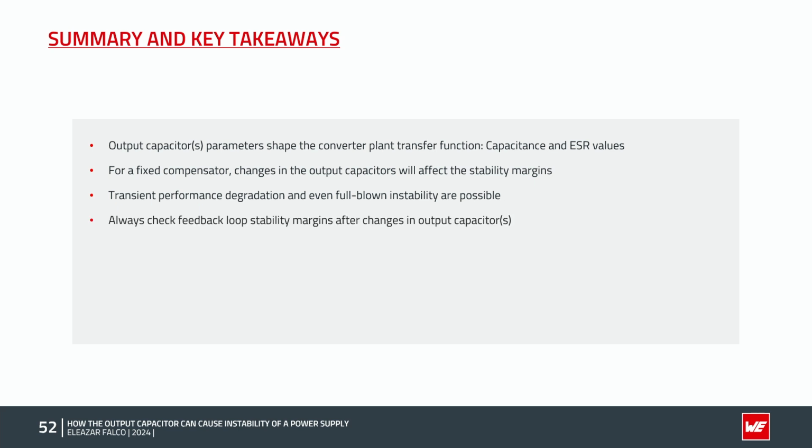So it is recommended to always check the feedback loop stability margins after any changes in the output capacitors are made, and redesign the compensator to keep good stability margins, even if you don't need it to ensure stability. It is good to have high stability margins.